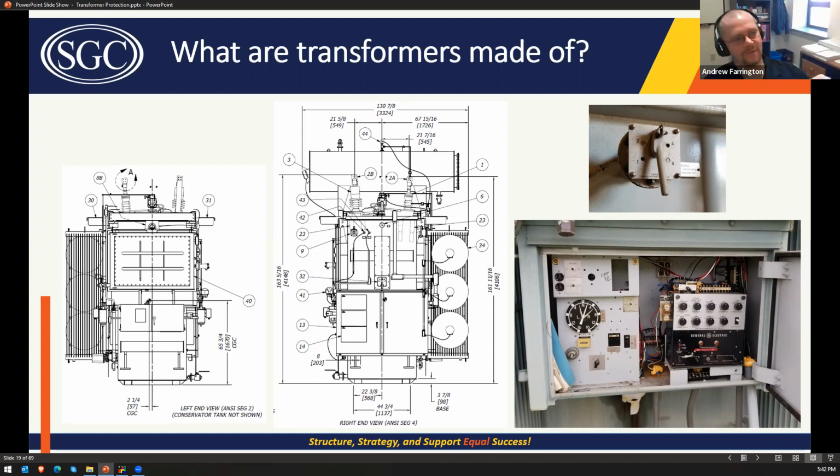Thank you. Yeah, so that's what you have, the no load tap changer. You do that once in a great while, right? Maybe load has shifted over the course of 10 years, and now you need to change the turns ratio of the transformer such that the LTC operates around neutral, or it's a new transformer going into a new substation, and we want to make it so that the LTC operates around neutral.